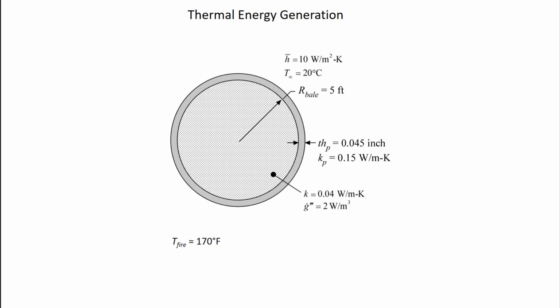It's basically rotting. And that exothermic reaction manifests itself as a generation of thermal energy, and if you don't let that thermal energy get out, you can find that the hay gets really hot. Hay tends to be not a very conductive material, and so a little bit of thermal energy generation at the center of a hay bale can cause a pretty severe temperature rise.